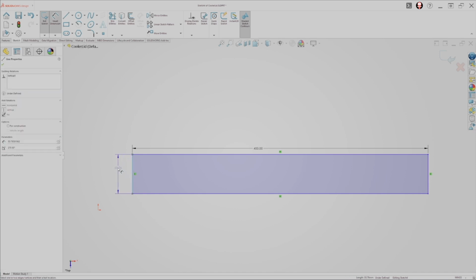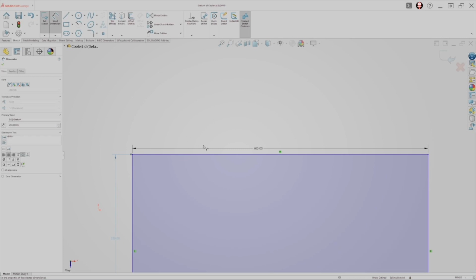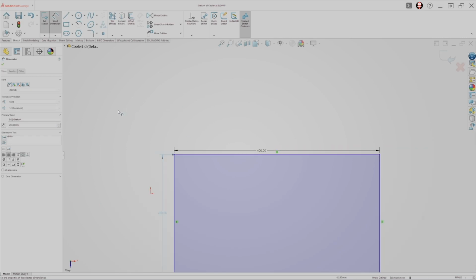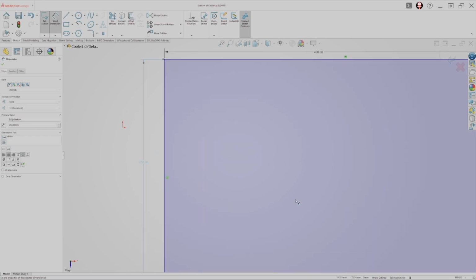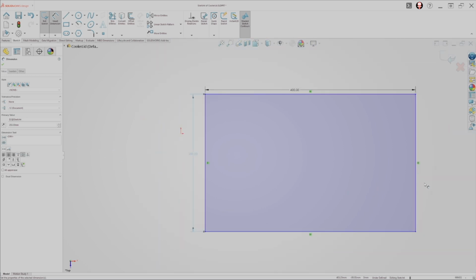Let's click on Smart Dimension and then click on that vertical line on the left. Now you can see it defaults to millimeters, which is fantastic. We will simply type 250 to specify 250 millimeters. I don't even need to type millimeters because it's defaulting to the metric system. So I can just press enter and then zoom out and see where I want to look at. Now that's looking great. I will turn the escape key visual aid back on so we can see it.